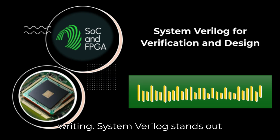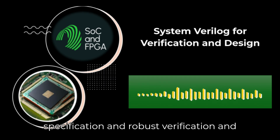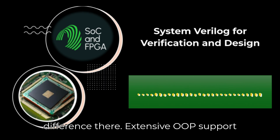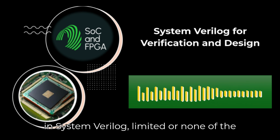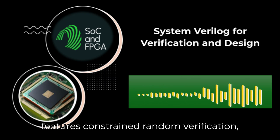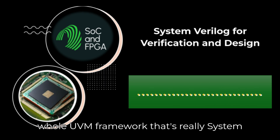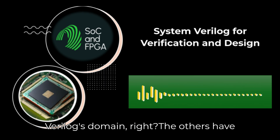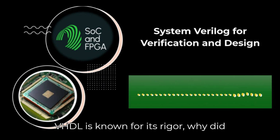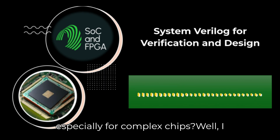SystemVerilog stands out because it's designed from the ground up as a unified HDVL for design, specification, and robust verification. And OOP support, verification features? Big difference there. Extensive OOP support in SystemVerilog, limited or none in the others. And those advanced verification features, constrained random verification, CRV, assertions, functional coverage, the whole UVM framework, that's really SystemVerilog's domain. Right. The others have very limited capabilities there. So if VHDL is known for its rigor, why did SystemVerilog seem to surge ahead in the broader semiconductor industry, especially for complex chips?